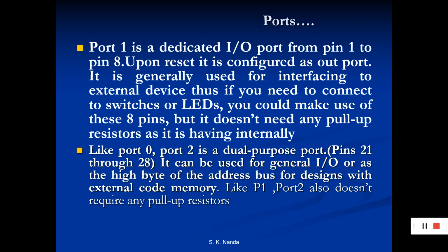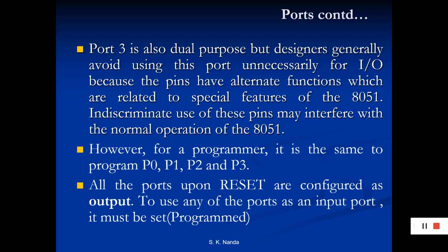For port 2, it is similar to port 0. When the external memory is used, pins of this port occupy addresses intended for external memory chip. This port can be used for higher address byte with addresses A8 to A15. When no memory is added, then this port can be used as general IO port similar to port 1. Like port 1, port 2 also does not require any pull-up resistors and it occupies pin number 21 to pin number 28 position.